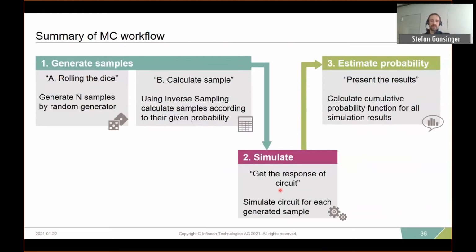And when the simulation is done, we are plotting our results in a normal probability plot or the quantile plot to see how our circuit will react to the variation in the process. So you can say this one is the processing steps, and this is what we will get when we measure our chips.